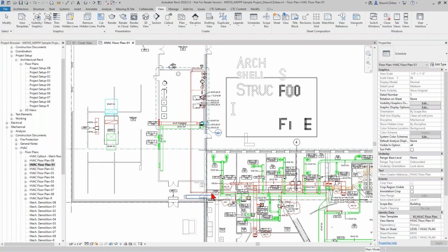And that works great for pipe and ductwork, but now if we're talking conduit and cable tray, there is no system name on conduit and cable tray. You cannot do this. It's impossible. So it's not impossible. You'd have to make yourself your own parameter called system name or run name or something like that, and then do some work to continually tab select the run, enter a value, keep that consistent so that you can filter for that. And that's just not convenient.